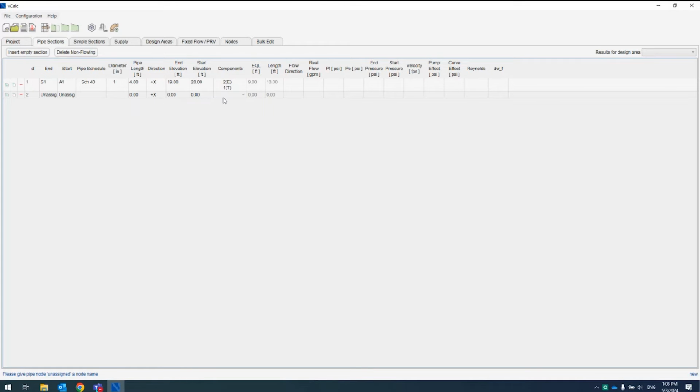And you could obviously continue filling this in as I did the very first row. We have two other options, which are these two green plus buttons here on the leftmost side, and then this one green plus and kind of the blank box. So this middle button, which says duplicate row when you hover over it, if you were to click on that, you'll see that it's going to carry over all the same information from that original row that I clicked it on. So it's got all the same pipe schedules, elevations, components.